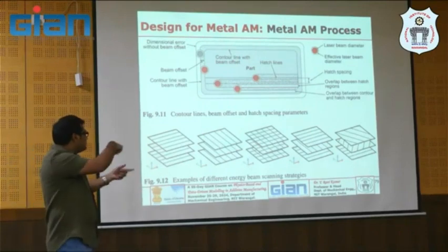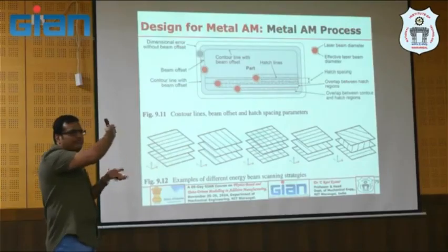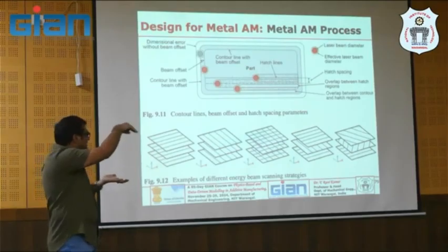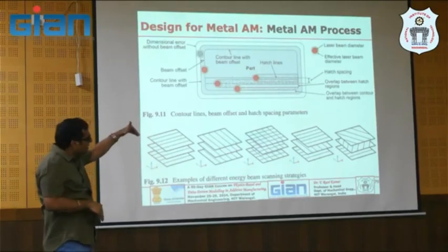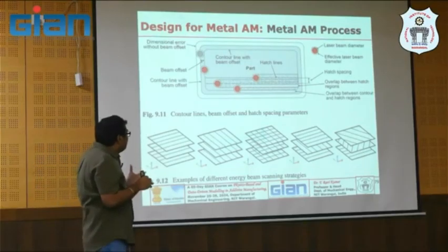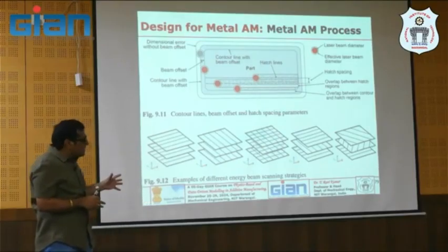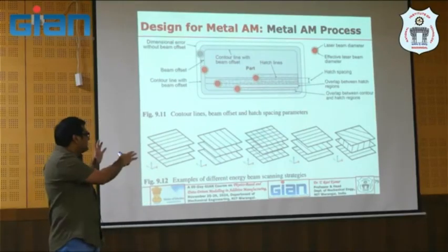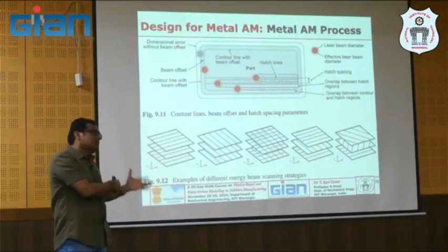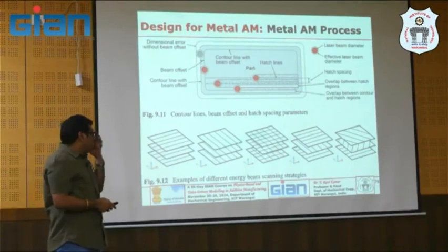For that reason you alternate or vary the laser paths with some inclination, say 40 degrees, 45 degrees, 30 degrees, something like that. You manipulate these parameters in such a way that residual stress is controlled.